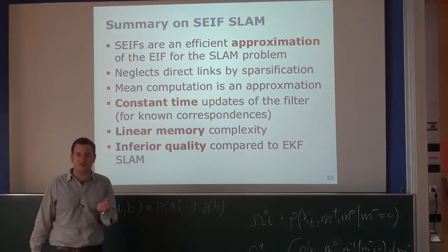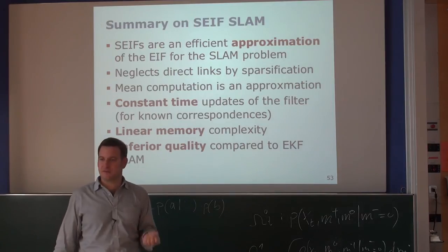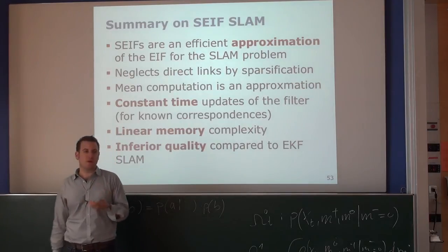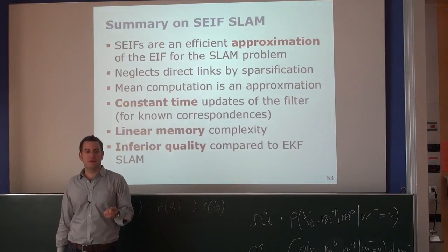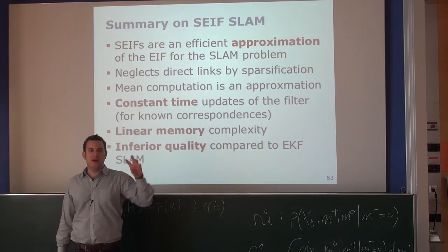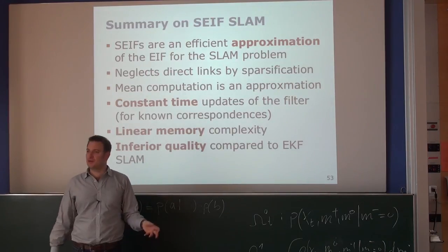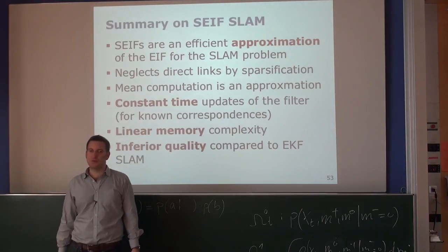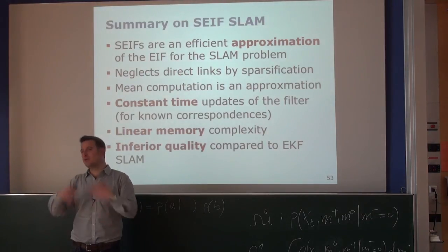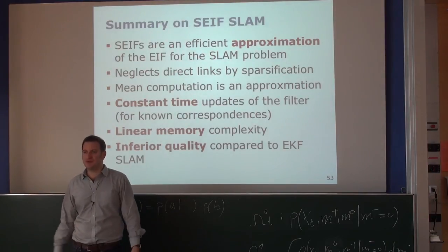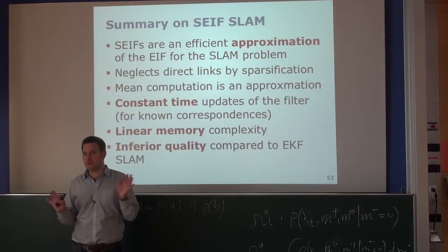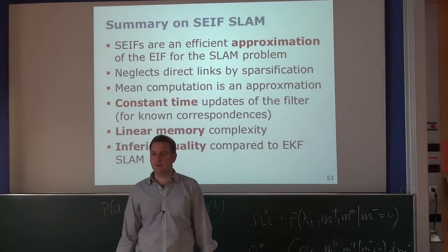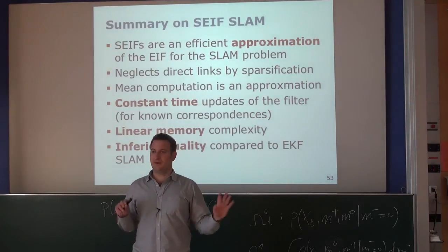It explicitly exploited some of the properties of the SLAM problem. Therefore, it was successfully used in SLAM, but at least I'm personally not aware of a lot of other applications of this framework. Because we have this special pattern that only a small number of dimensions are changed by the update step, which is just the position of the robot, and at every point in time I observe only a constant or limited number of features or other variables. In this situation, this technique can be used in an effective way. Any questions about that?